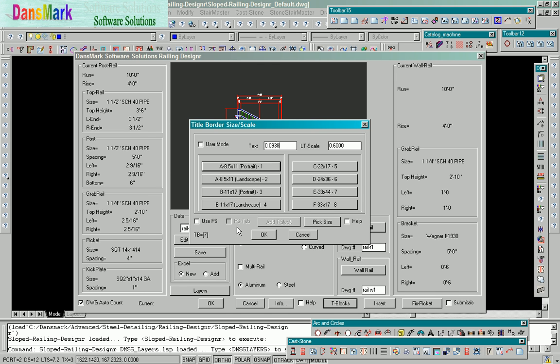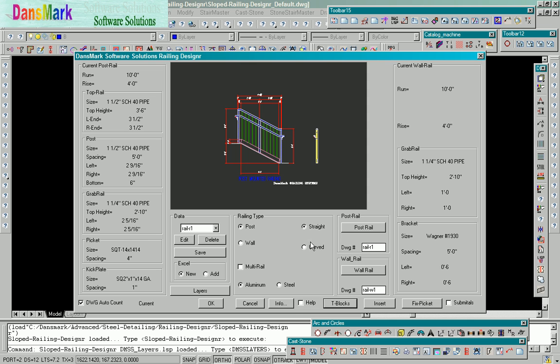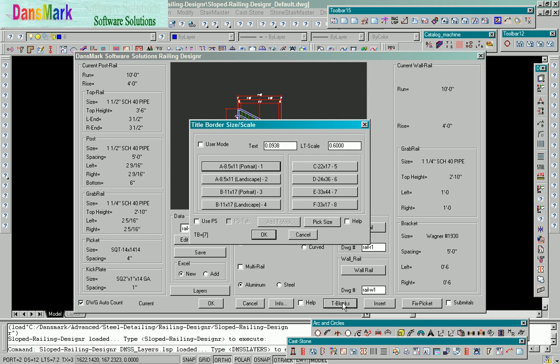So it will also use your title block. Not only that, but it'll put it in user mode so that you can use it as a standalone inside of model space, and it will also create a Paperspace tab for you. And if you have that checked, use Paperspace mode, it will become the default.